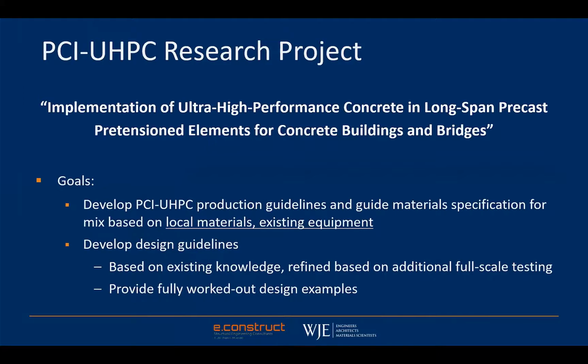Excuse me, as the title implies, the goal of the project is to create information for precasters to support the production and structural design of big members. So we're talking about things like bridge girders as long as 250 foot in span, and building floors 60 by 60 foot in size. So there are really two components of this project. There's a materials component and a structural component. On the material side, the intent is to provide guidance on how to design and produce cost-effective UHPC mixtures based on locally sourced materials.